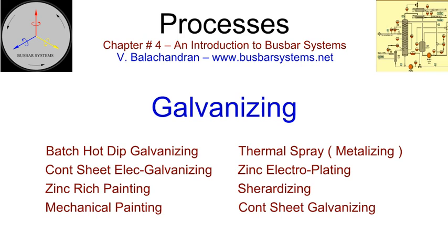There are different galvanizing processes, and the selection depends upon the size and shape of the component, coating thickness, and service conditions. In the bus industries, galvanized sheets are used as enclosure material. Formed and rolled sections of steel are galvanized and used as support structures. Galvanizing of fixings and hardware is carried out especially when they are installed outdoors.